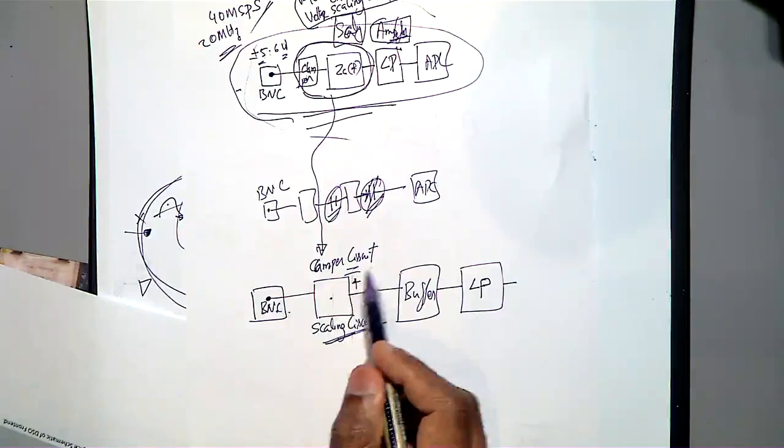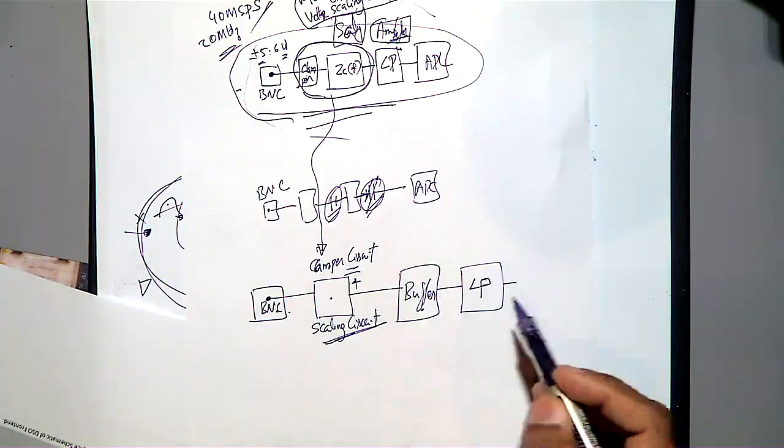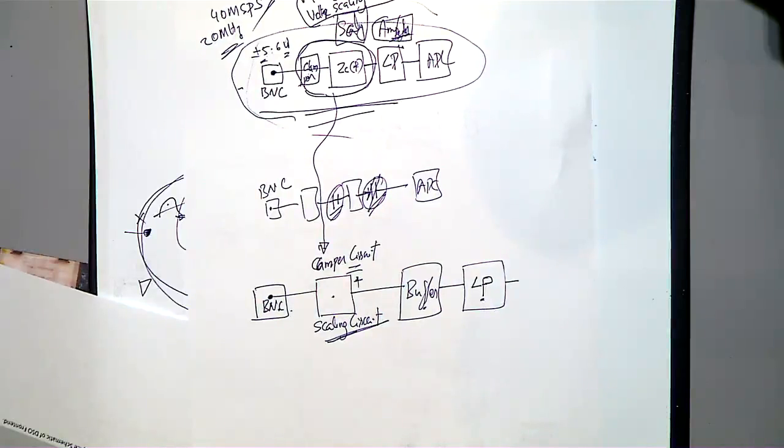This block, because you need to cut off your voltage at plus or minus 5, and you also need to tune the impedance, I drew as one block. Then it is good to have a buffer, then a low pass filter. But as I said, when you have a small signal, you need some amplification, so we can add one amplifier here.